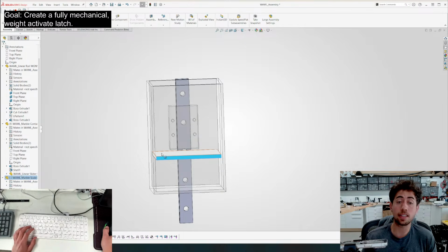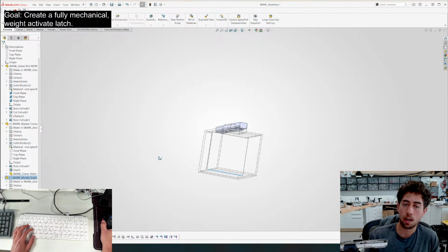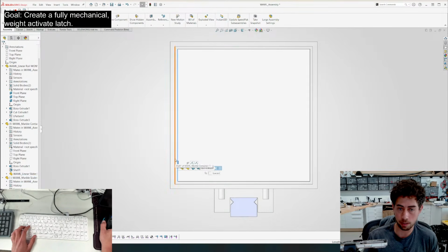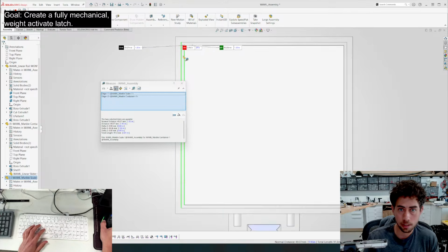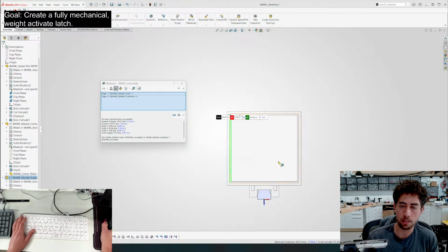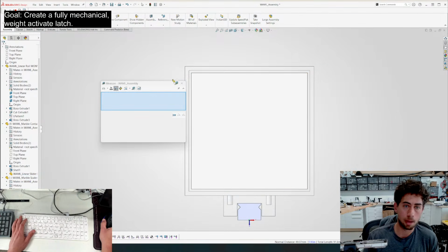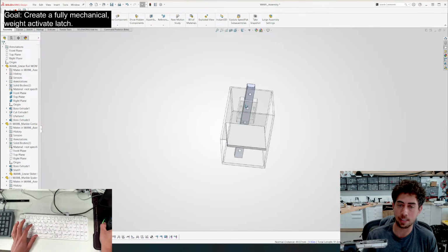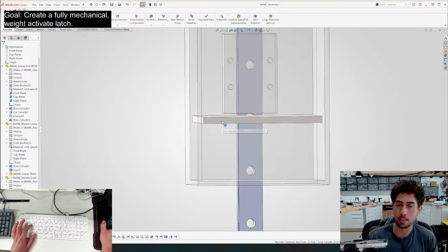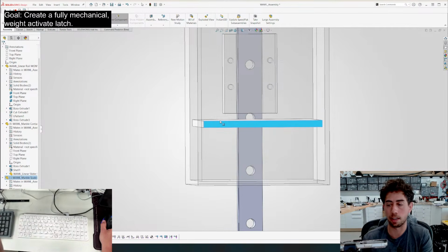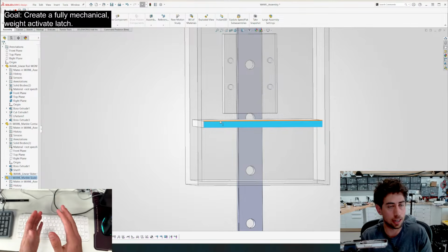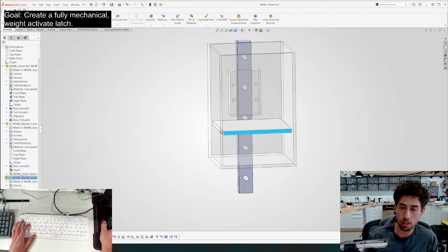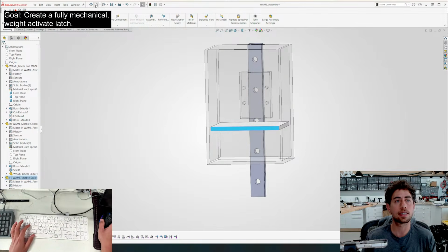For tolerance, we'll get into tolerances actually, but right now, this is a perfect situation to look at. So this is a lot of tolerance right here. We're looking at almost more than a millimeter. I use millimeters. It's different depending on what we're doing. But in this case, where I have this thing that's free sliding inside something else, this is too much tolerance. There's going to be a little bit of wiggle. It's going to wiggle inside the thing and it's going to jam, but we're going to fix that also. But for now, we're just trying to get the latch. So let's draw the latch next.